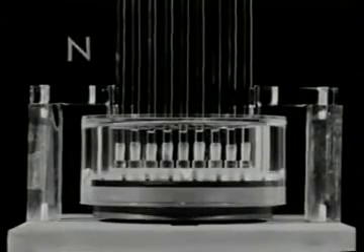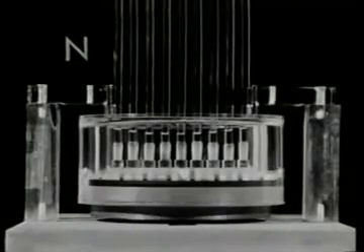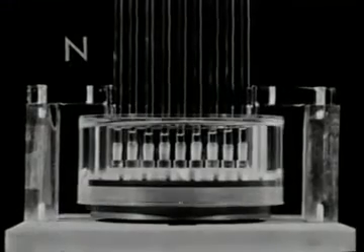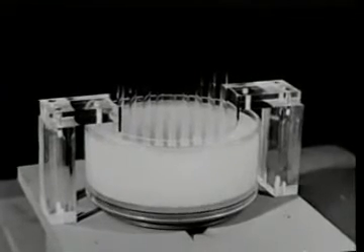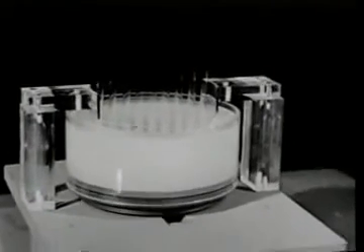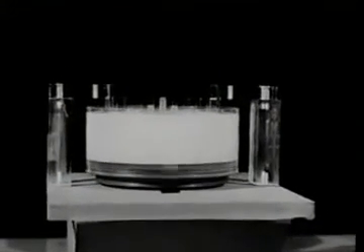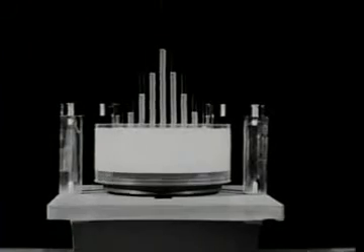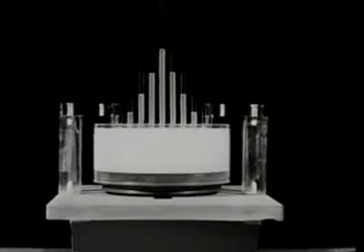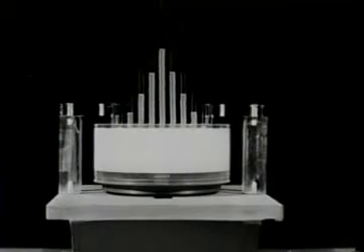If the fluid is Newtonian, the height of the fluid in the tubes at steady state is a little less near the center than toward the outside. For a non-Newtonian fluid at the same speed, the force normal to the stationary plate may be considerably greater toward the center. Although the steady-state stress distribution between the plates is attained almost immediately, again it took several hours for the levels in the tubes to reach their final positions. Indeed, quite high stresses can occur near the center, and this principle has been used in the design of a pump for molten plastics.